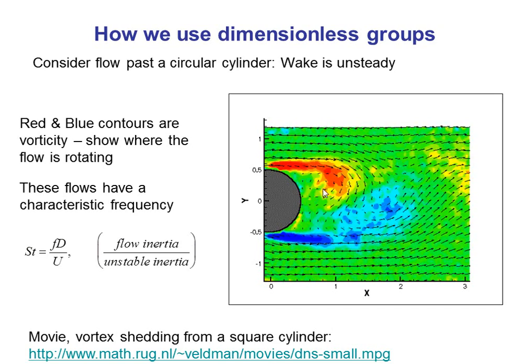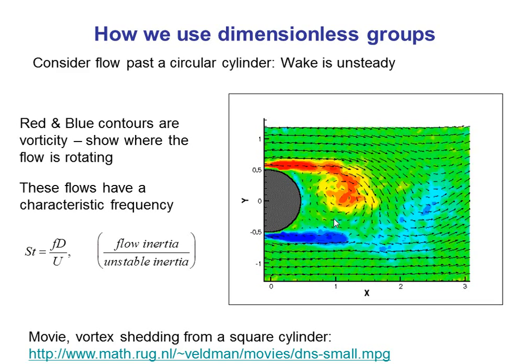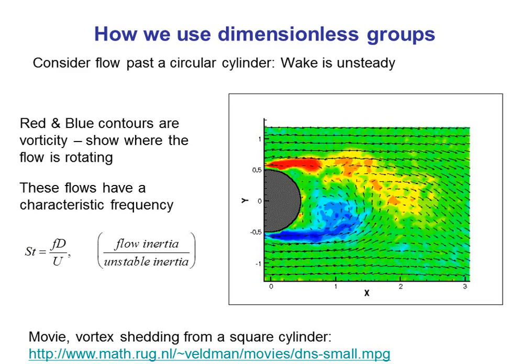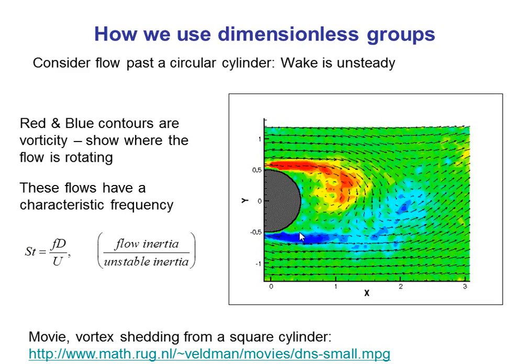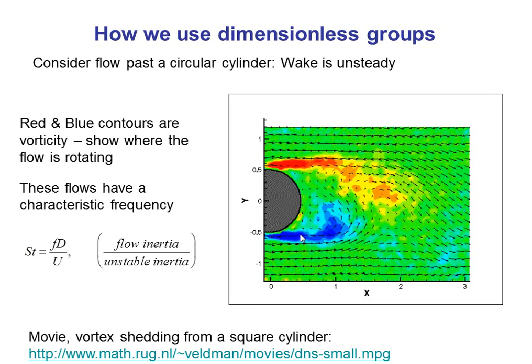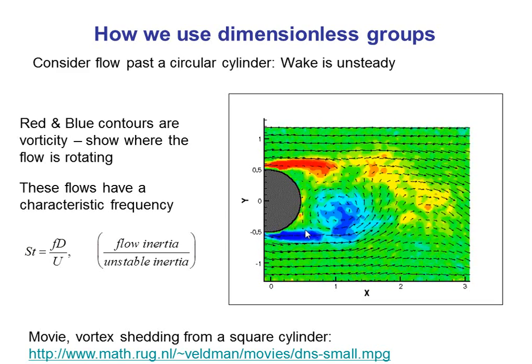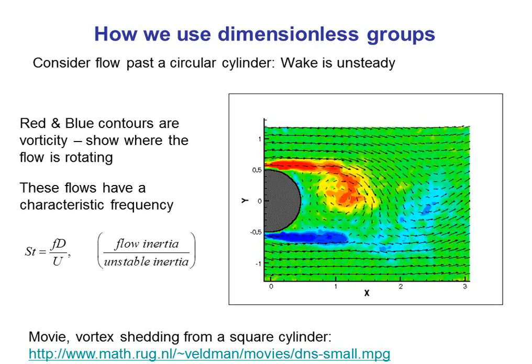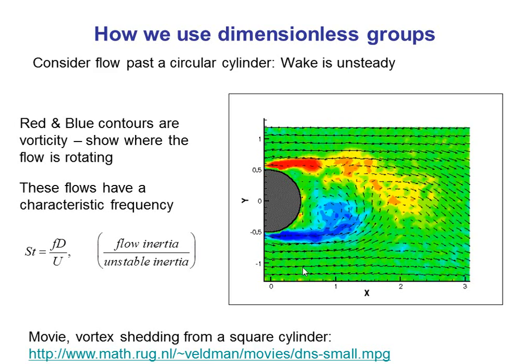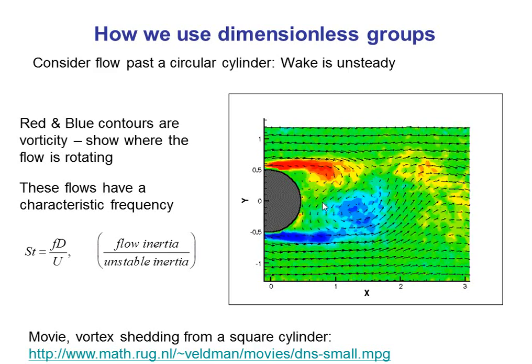Inside here, there's a lot of losses and unsteadiness, and your Bernoulli equation does not apply because there's a lot of shear. From the shearing you can see there's a big gradient in velocity, from fast moving to slow moving, and a lot of losses there. So outside the flow is irrotational; here the flow is rotational or viscous, or whatever you want to call it.